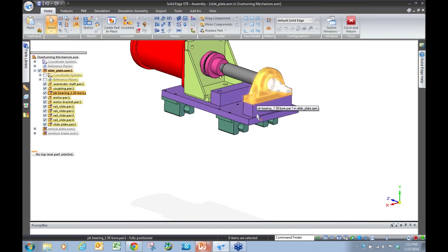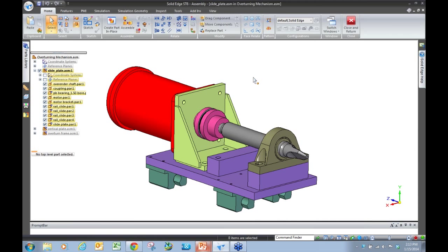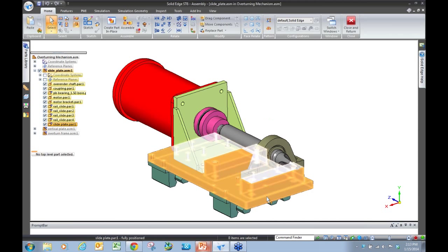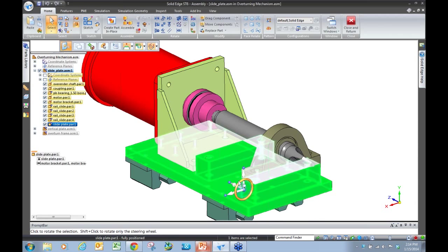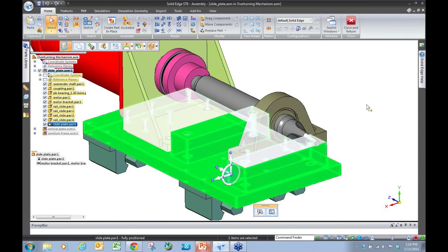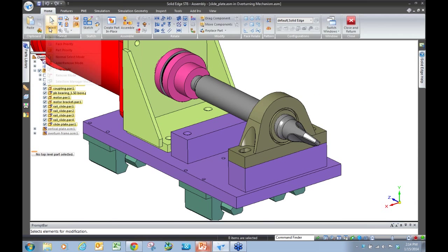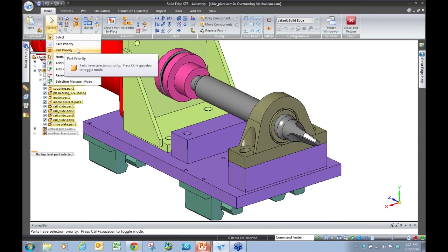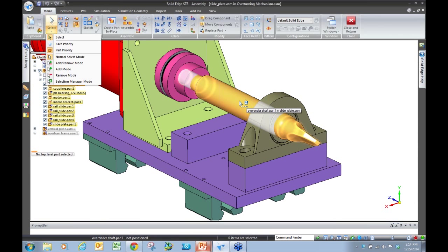So notice I've got a little side plate assembly up here, a vertical plate, and I've got a frame assembly. Well, same things that we're used to back in the other versions. I can activate this assembly here and edit this in place. Open that up, and if I hit Control Q, you can see there's the actual assembly. Hit Control Q again, and it'll toggle it away. So here I have the little sub-assembly. It's already active. I'm working within it, and I want to make some changes to this.